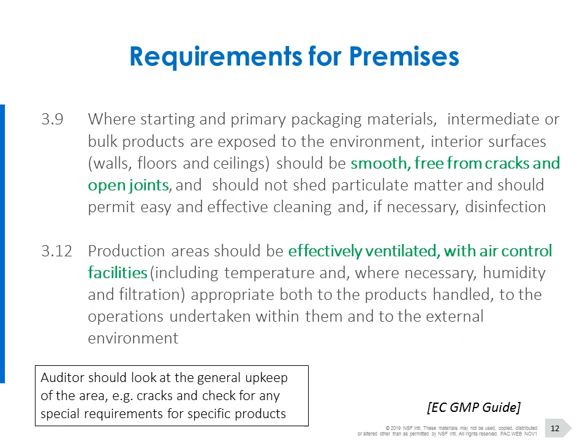Again, looking at the actual standards for premises, it's very similar for most manufacturing facilities for medicinal products. Critically, there should be smooth surfaces, free from cracks, no open joints, and should not shed particulate matter, and should permit easy and effective cleaning and, if necessary, disinfection.